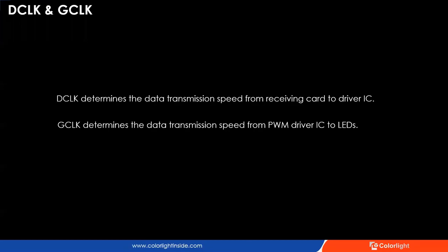A regular driver IC does not have GCLK. The LEDVISION software will not show the GCLK option either if you are using a normal driver IC. A PWM driver IC will increase the screen's visual refresh rate because it divides the LEDs' on time for a frame into multiple equal time pieces to improve the screen's visual refresh rate.